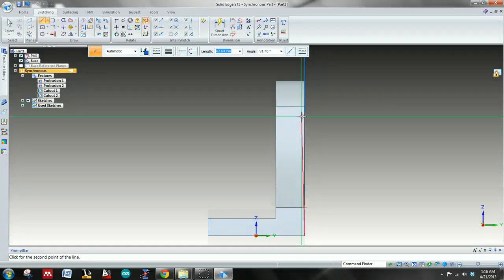So the center of that is going to be located at 70 millimeters, angle 0, enter. That's where the height is, okay? And we need to come to the very center of this thing here. So the center of it is going to be, since it's 16, 8 out, angle of 180, enter, okay? And so we need to set it to be 12 millimeters above that center point. So 12, angle 90, enter.